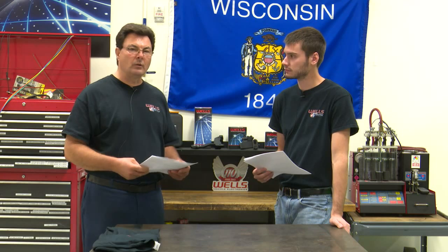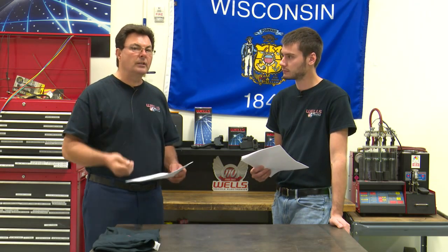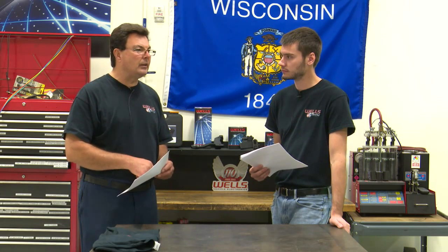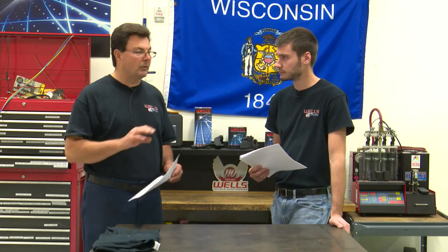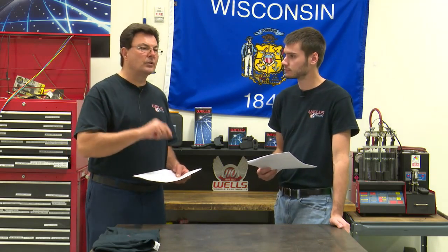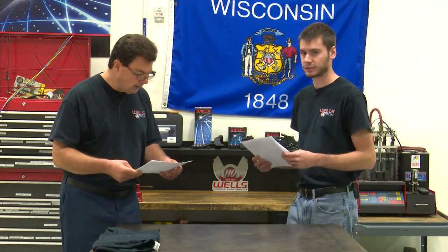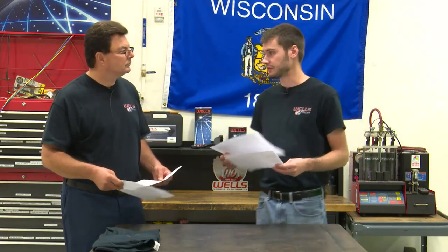If you have to drive it more than one time, do so. And bring it back to the shop, run the codes again. Even though you may not have a light on there, you may have a code already, like a pending code. And then start with the lowest code, the lowest number.